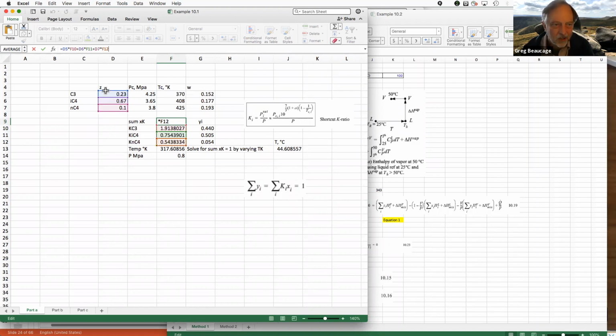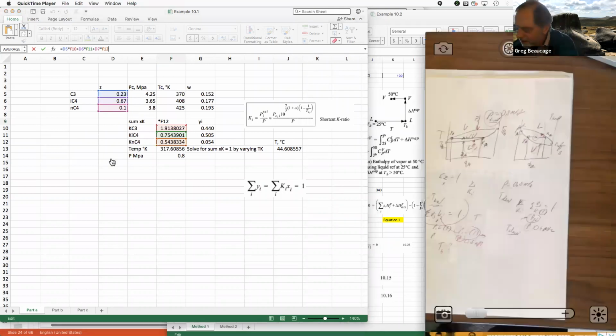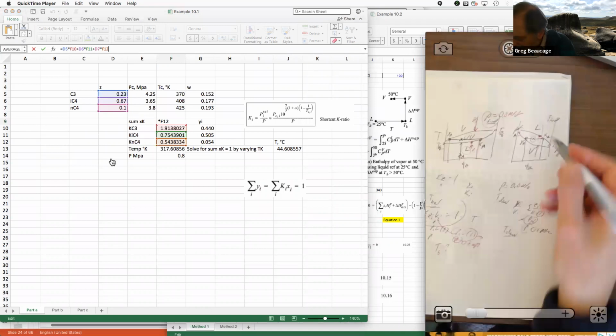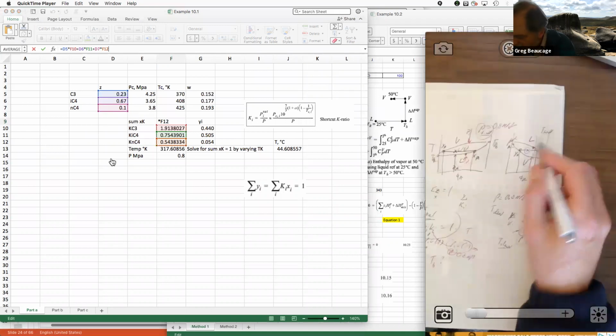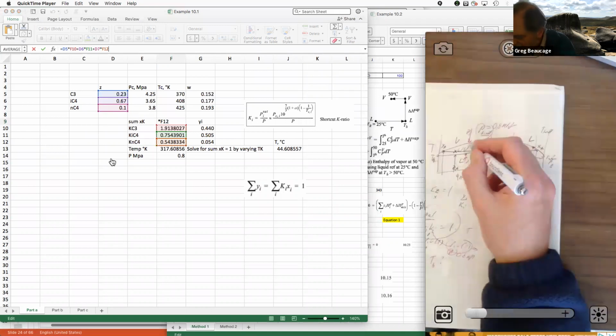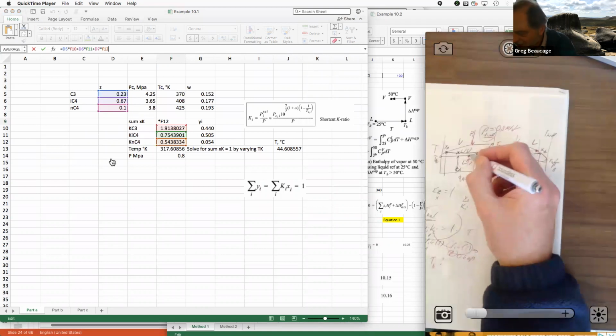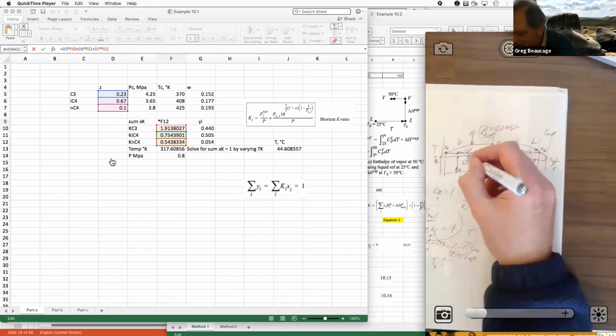So Z, even though it's coming in as a vapor, you want to totally condense it. So you're going to form a liquid. You come in as a vapor, Z, you want to form a total liquid, but you're trying to calculate this temperature and the composition at that temperature.